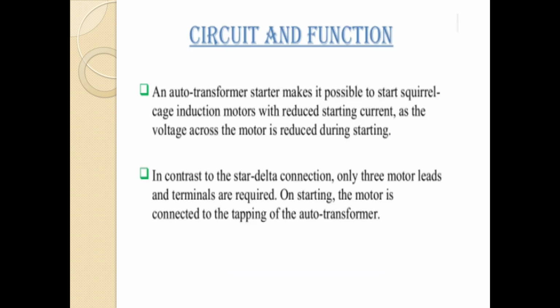The supply terminals 1, 3 and 5 are on the movable handle and the motor is connected to 2, 4, 6 through the OLR switch. OLR means overload release coil. Low voltage protection is given to the motor by UVRC.